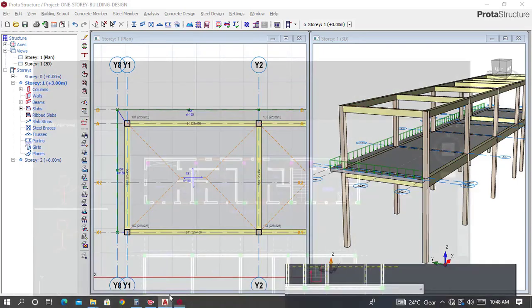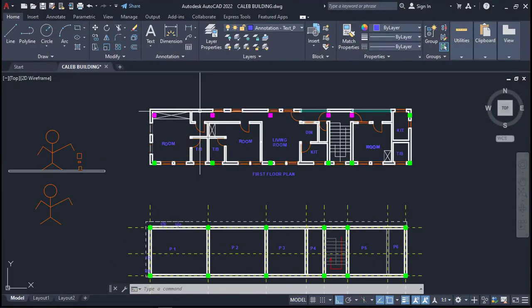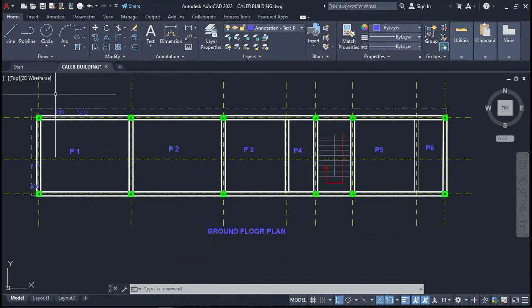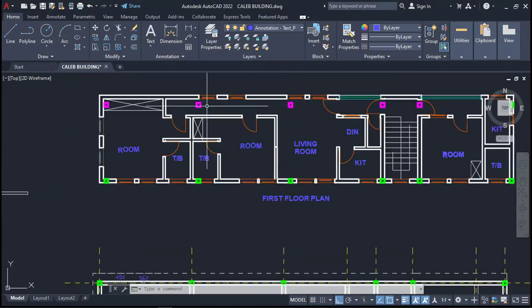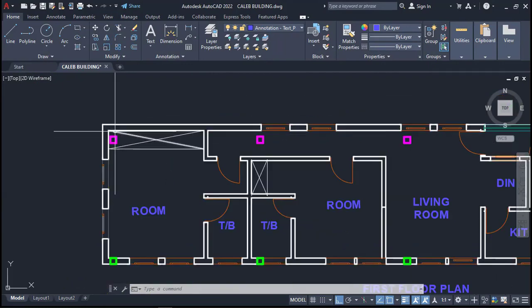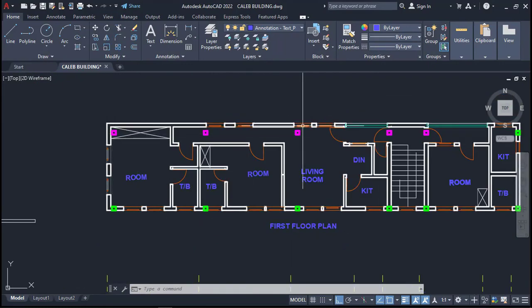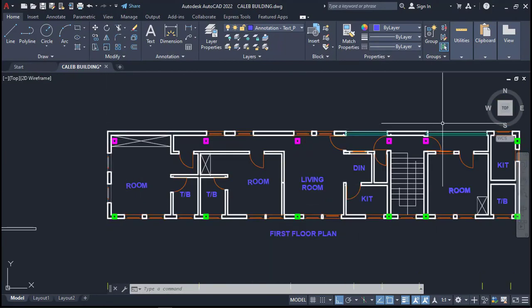If you look at this AutoCAD plan which we are designing for, you can see that on our ground floor plan there is a cantilever, as you can see here. So there is a change between the ground floor plan and the first floor plan, which makes our columns come out in the empty space on the first floor plan. So we will now have to shift and adjust, sorry, not all the columns, just these columns that are showing pink here on the first floor area.